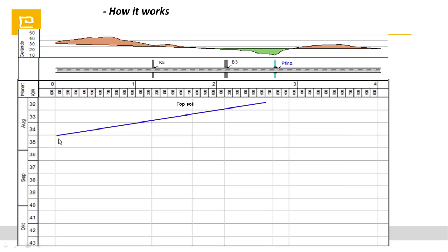It doesn't only give an idea of just a start and end, because TILOS also has a dynamic way of insight, so that I can get insight into which activities I am doing and when. For example, if you ask me the question when we will be doing the first kilometer, the answer is that I can come to the location, go down, touch the activity, go left, and see that at the end of the 2nd week of August we are going to work in the first kilometer.